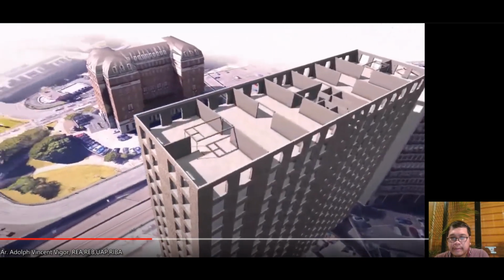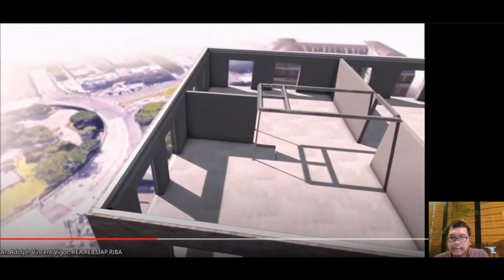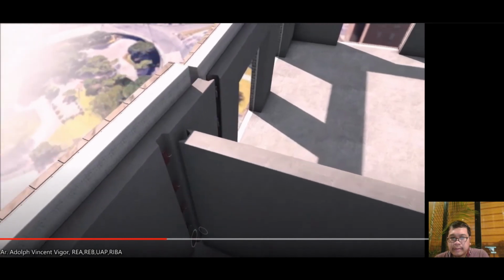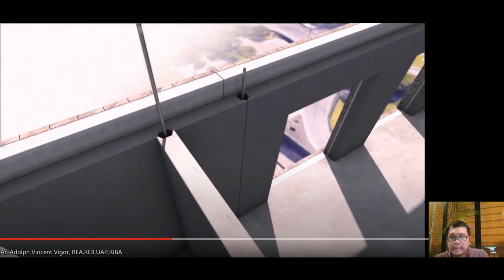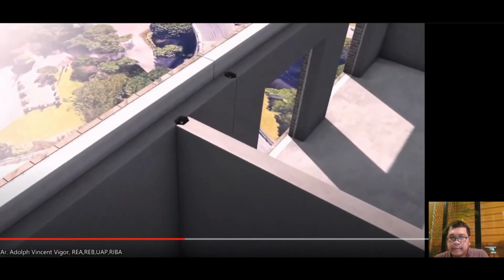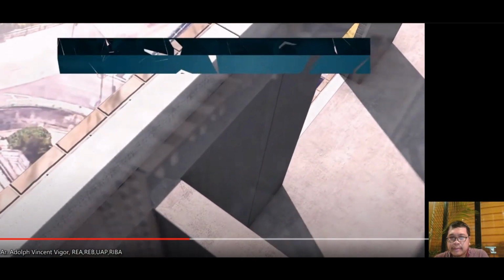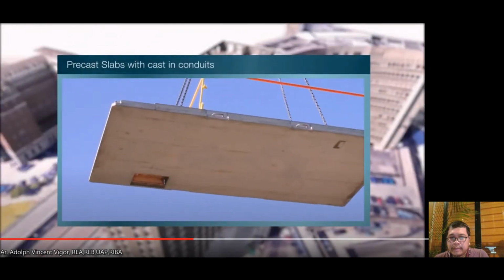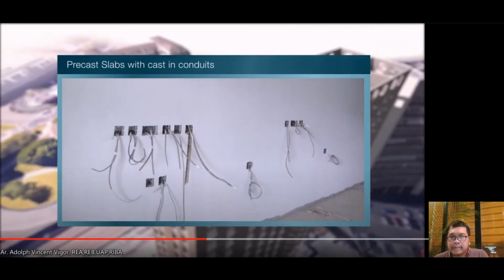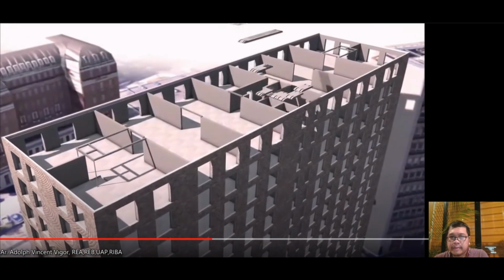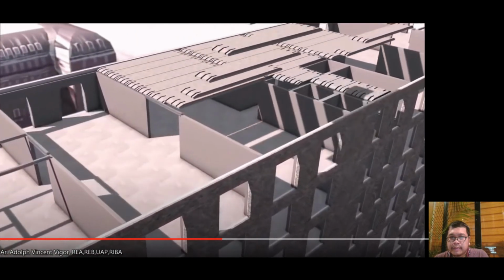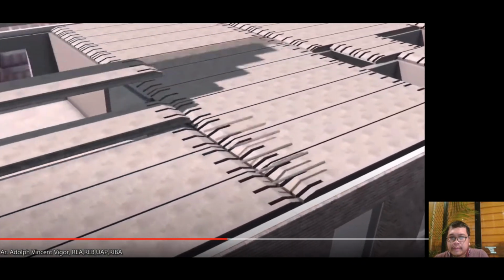Installation is clever but simple. To satisfy Approved Document A of the building regulations, the sandwich panel walls and internal solid walls have continuous vertical ties. All floors are horizontally tied to their supporting walls to provide a three-dimensional tied structure. Placed on top of these are precast slabs that cover an entire room, with the conduits for lighting and recesses for bathroom pods. Alternatively, hollow-core precast concrete planks are used for longer spanning areas. These flooring units are lifted onto their final bearing directly from the delivery vehicles.